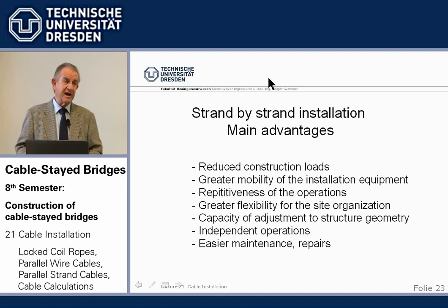The parallel strand fabricators claim they can exchange any individual strand and replace it, because it's just reversing the construction method. And that, of course, is important. If we have corrosion, we do not need to replace the complete cable. We can replace individual strands. How much that really comes true in 20 years on site, I'm not sure, but theoretically it's possible.